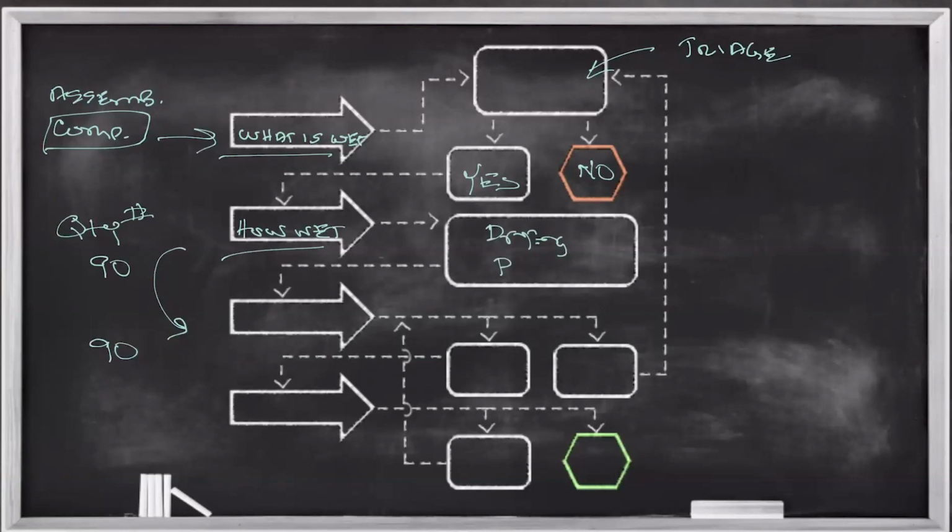And your drying plan is going to include your class of water. Sorry for the horrible penmanship today, but that's going to establish your class of water. That's where you're going to then, based on that class of water, establish the dehumidification plan that you're going to deploy, how you're going to erect your chambers, et cetera. That's where the drying plan comes into place. And that's kind of the thinking process of day one, if you will, of the mitigation effort.